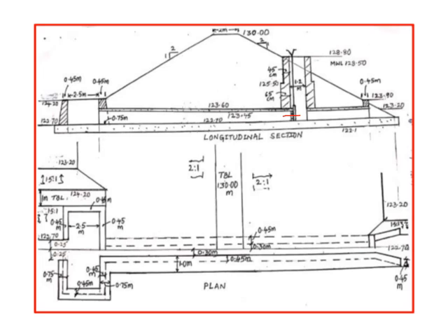122.7 plus, so this is 0.75, I think, the depth of the water. So 0.5 plus 0.75 plus 0.5, I've given somewhere around 1.25 into 1.5. So that comes to about this TBL RL of up to 124.2. So therefore, the ground level is fixed at 123.2. So we have to see the ground level at the site, which is 123.2.